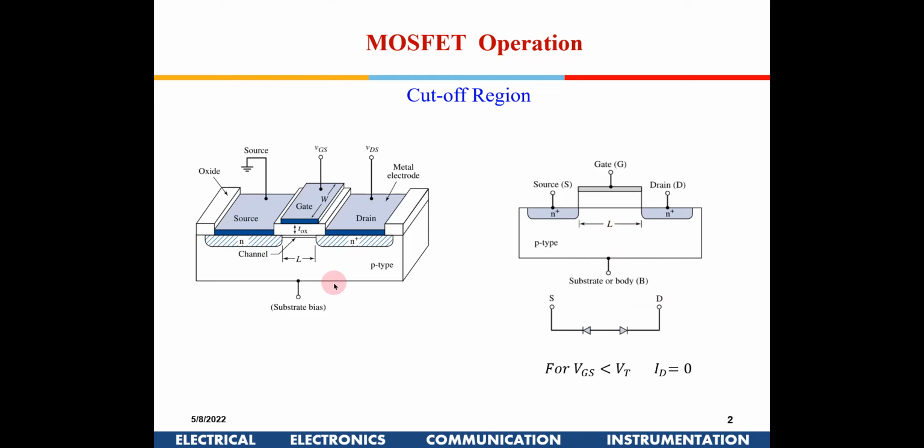So let's take a quick review of how a MOSFET operates in the long channel, the normal MOSFET operation. If you see here an N channel, how is an N channel made? You have a P substrate, and then you cut open two windows, and then you do implantation of N dopants. So you have a source region and a drain region out here, and between these two regions you have something known as the channel, which is intrinsic P itself. So this P is intrinsic. Actually, the doping concentration generally for this is around 10 to the power of 15, right?